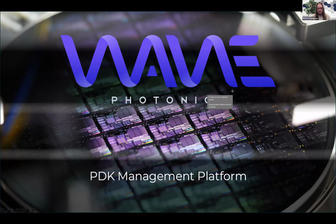That includes having those PDKs accessible in the different EDA tools so that you can start using them in your current design flows as quickly as possible. So we ended up building a lot of infrastructure for taking those component libraries, having a system for versioning them, having a system for generating the S parameters, which are used for compact models, and then wrapping that all up and publishing it to a website where a user can simply log in and download to access.